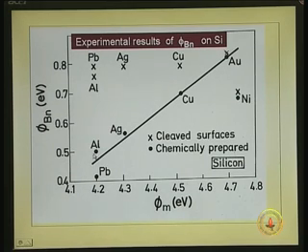Now, take this cross. The cross is made on a surface which is freshly cleaved. You cleave silicon, you get all those dangling bonds hungry for grabbing electrons, surface states. If you make a metal semiconductor contact, you get a barrier height which is practically independent of phi m.